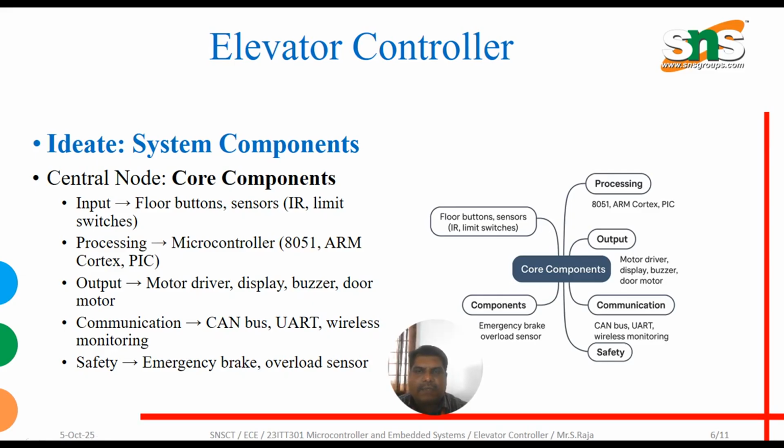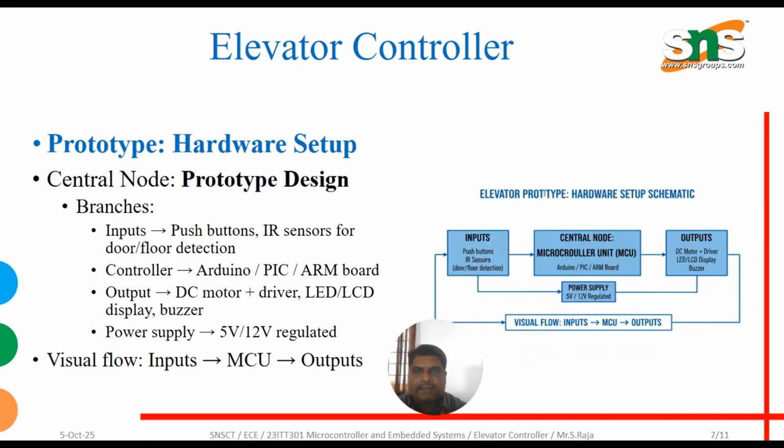The inputs are the floor buttons and sensors, then the processing is the microcontroller, 8051 or ARM Cortex or PIC microcontroller. Then the outputs are the motor driver, display devices, buzzer or door motors. Then the communication may be defined using UART or CAN bus or wireless monitoring devices. Finally, safety is ensured by using an emergency brake or overload sensors.